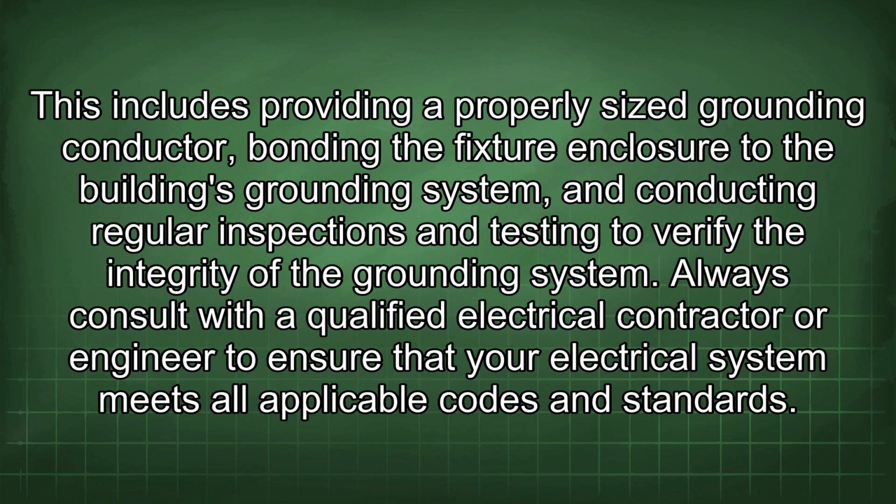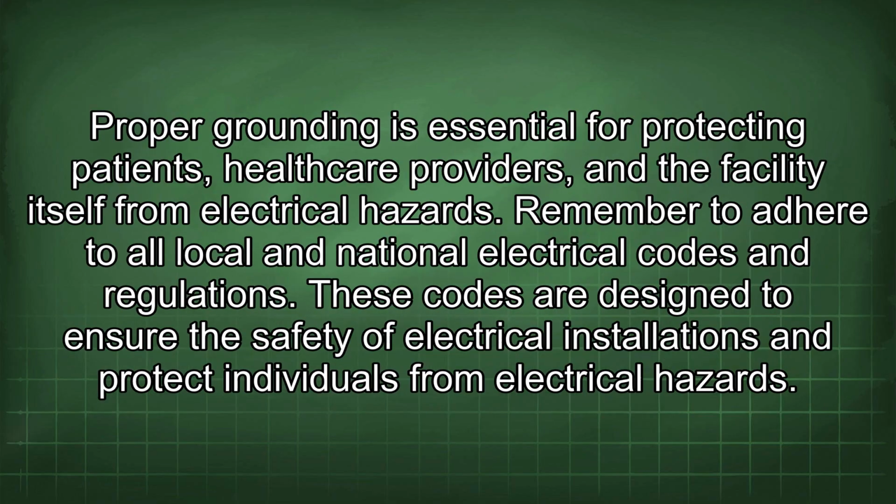This includes providing a properly sized grounding conductor, bonding the fixture enclosure to the building's grounding system, and conducting regular inspections and testing to verify the integrity of the grounding system. Always consult with a qualified electrical contractor or engineer to ensure that your electrical system meets all applicable codes and standards. Proper grounding is essential for protecting patients, healthcare providers, and the facility itself from electrical hazards.